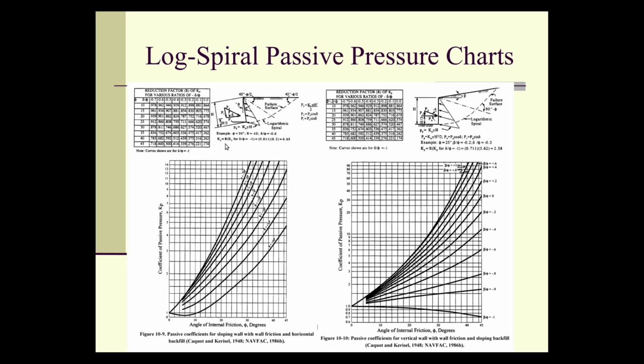If you just look at the chart at phi of 30 and theta is equal to, don't forget, minus 10. In other words, the wall is actually leaning from the top, it's going left. You go up to theta minus 10, and you end up with something about, let's see, about 0.811 according to this. No, excuse me, 8.2, I'm sorry. 30 comes up, you hit minus 15, somewhere in the middle is 8.2, somewhere around right through here.